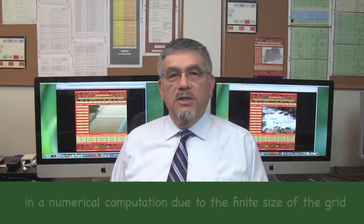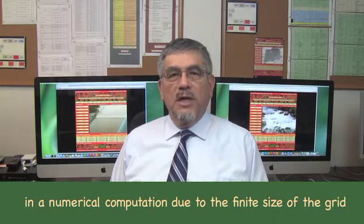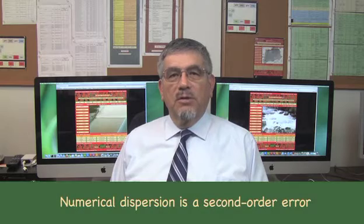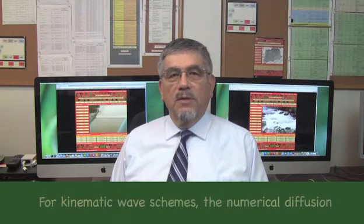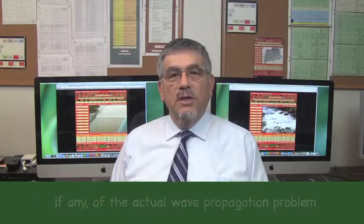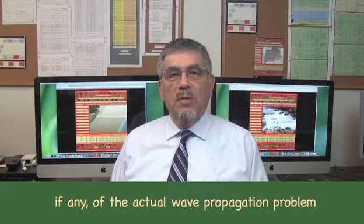Unfortunately, depending on the prevailing Courant number, these schemes introduce a certain amount of numerical diffusion and dispersion. Numerical diffusion and dispersion arise in a numerical computation due to the finite size of the grid. Numerical diffusion is a first-order error. Numerical dispersion is a second-order error. For kinematic wave schemes, the numerical diffusion is arbitrary and not related to the physical diffusion, if any, of the actual wave propagation problem. Therefore, a numerical solution of the kinematic wave equation remains essentially a conceptual model, not necessarily related to the actual physics of the phenomena.